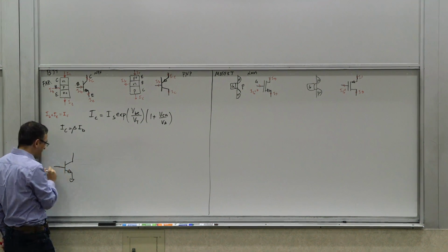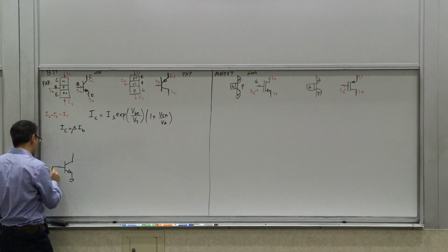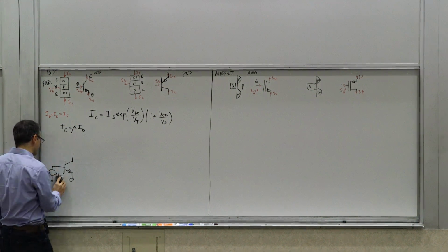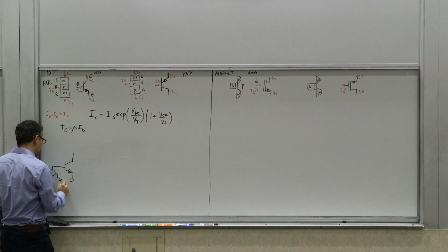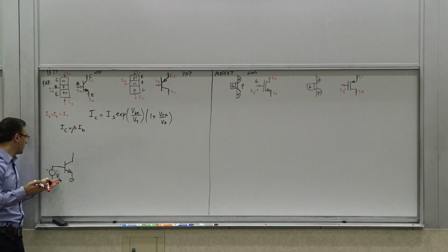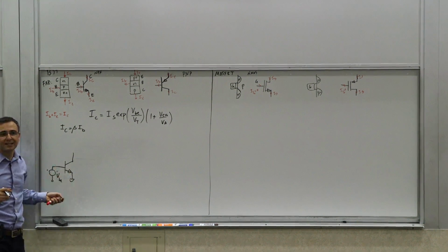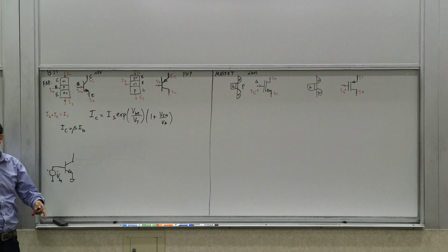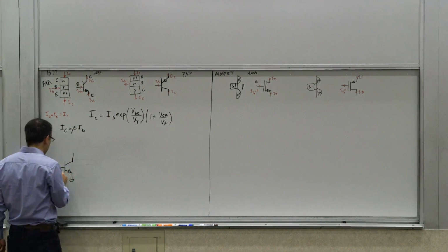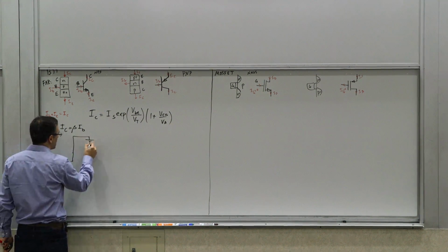So let's say now you're in this situation, and then you have a voltage, right? So you can have, let's say, a VBE. Let's show it as a source, capital V with lowercase b. The notation we use here is that we combine capital and lowercase. If you use all capitals, it means that it's just the DC. And if you use all lowercase, it means the fluctuations or perturbations that we're going to be talking about. So that's the notation, a little bit of this, a little bit of that. Some books use a different combination.